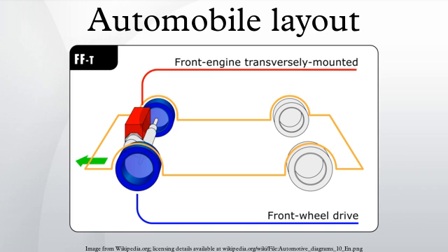Due to geometry and packaging constraints, the CV joints attached to the wheel hub have a tendency to wear out much earlier than the universal joints typically used in their rear-wheel drive counterparts. The significantly shorter drive axles on a front-wheel drive car cause the joint to flex through a much wider degree of motion, compounded by additional stress and angles of steering, while the CV joints of a rear-wheel drive car regularly see angles and wear of less than half that of front-wheel drive vehicles.